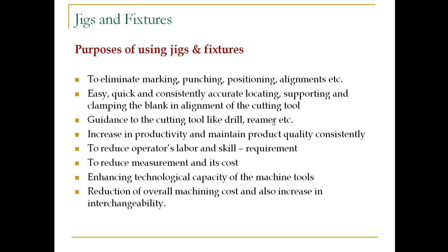Guidance to the cutting tool like drill and reamer. Cutting tools like drilling tools and reamers have to be guided in a proper manner by means of a jig bush ultimately. Next, that is increase in productivity and maintain product quality consistently. So with that, obviously the productivity will be increased and product quality can also be consistent, right? And to reduce operator's labor and skill requirement, you can use any normal operator also who is not skilled.